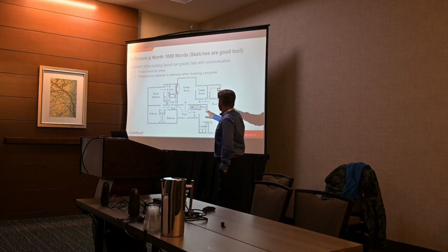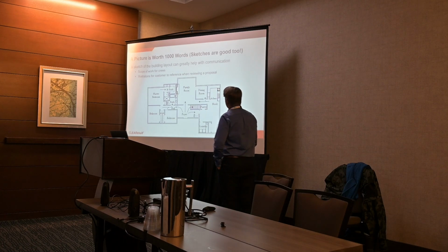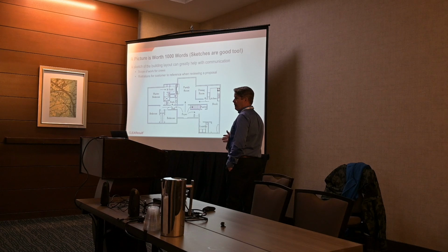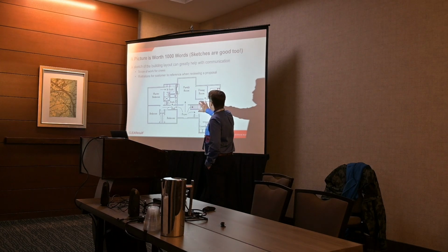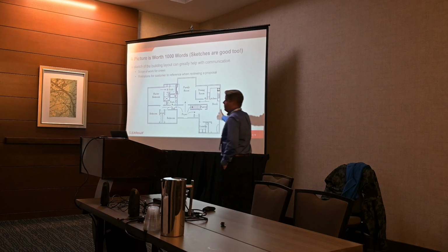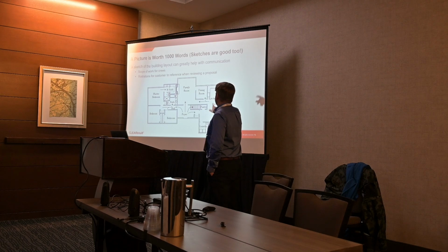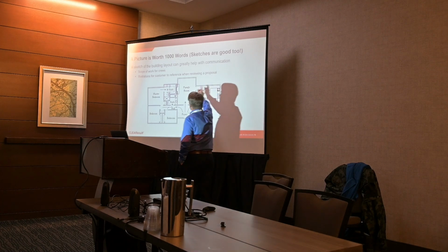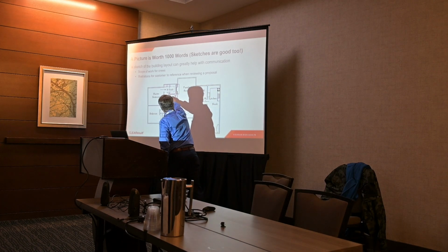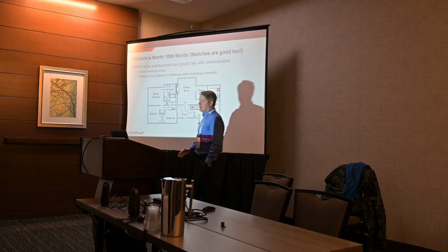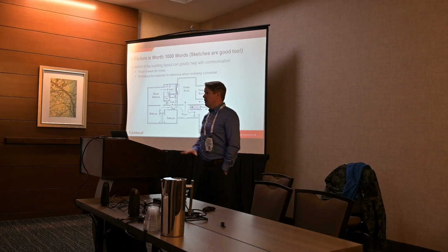Now, doing this actually helps out in a couple different ways, right? This helps out the air sealers. If you do an interior walkthrough and you put the stuff in here, it's a lot easier to find air sealing details from inside the house than in the attic. It's easy to see a recessed light from down here, not so easy in a dark attic when it's underneath the insulation. So drop soffits, masonry chimney, wet walls, isolated top places they might not find, that sort of thing, are all things you can put on a sketch that helps the air sealer.